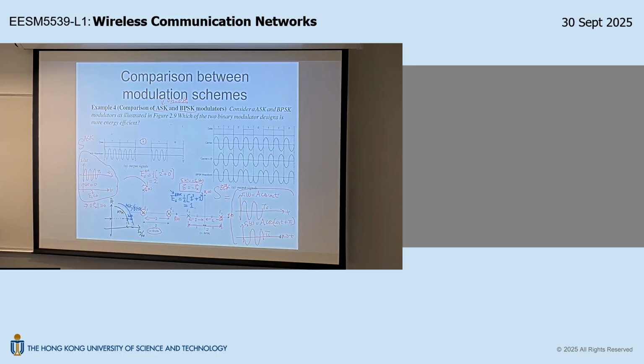Now, if you want to maintain the same error probability, then what can you do with this APSK? If you want to maintain the same error probability as the QPSK version, the only thing you can do is you need to put the 8 points over a bigger circle, right? This cannot be a unit circle. This must be a bigger circle, let's say this is alpha. In this case, you want to set this guy to be square root 2 so that it has the same error probability, right, as QPSK. And then you figure out what's alpha. So alpha must be bigger than 1, okay? So you can also calculate how much bigger, okay?